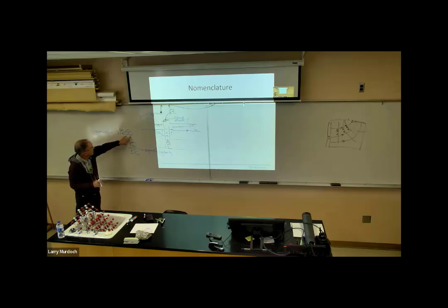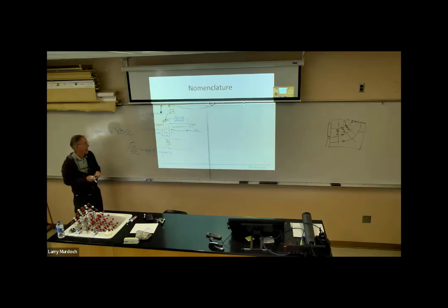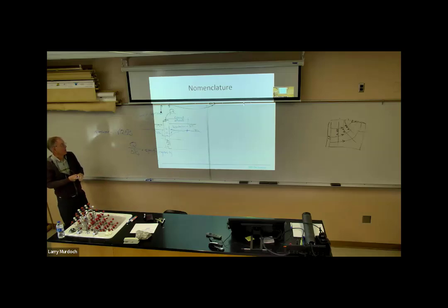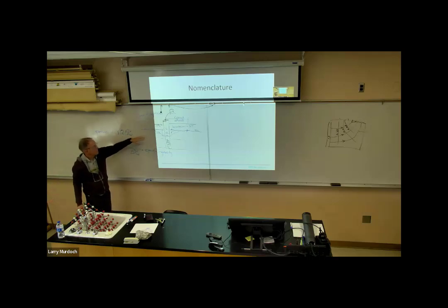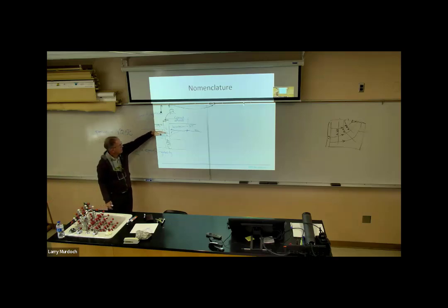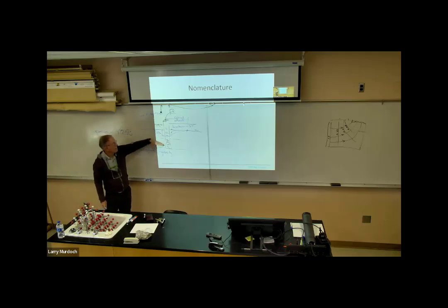To this drawdown, we would also add in that distance to give us the total amount that we have to lift. This ends up being important because if you have a very deep well, then you start to have significant amounts of drawdown that can then increase the power that is required. And if you have a deep well, maybe eventually the drawdown is high enough so you can't even lift the water out of the well.